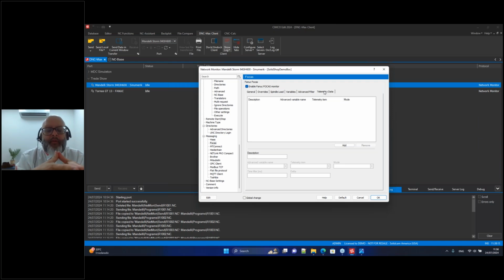Another example I implemented in the same location was welding. Welding is a very difficult process because it's a special process. So you need to control the parameters so you have the outcome, the result you expect. It's not like machining, where you move the dial on the machine a tenth of an inch, and then you cut a tenth of an inch on the material. Welding is not that accurate, but you need to control gas pressure, temperature, welding speed. All these things are important because if they are not okay, then your weld will not be good, right? So they wanted also to track that.